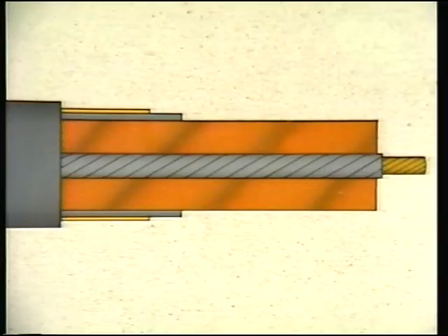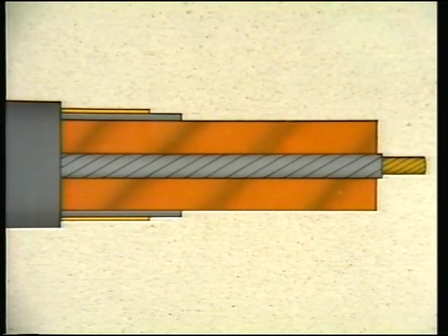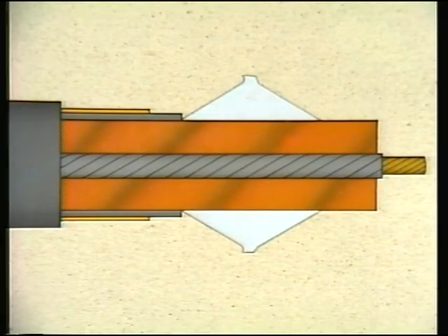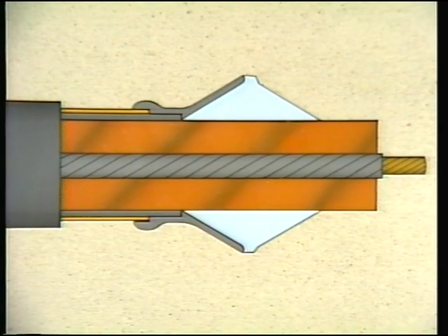Cable terminations use two different methods of controlling voltage stress. One method involves increasing the thickness of the insulation, and the other involves changing the cable's electrical field. With the first method, the cable insulation is increased at the end of the insulation shield layer by building a cone of insulating material. The insulation shield is then extended to the high point of the cone with semiconductive tape. The addition of these two materials decreases the concentration of voltage stress.